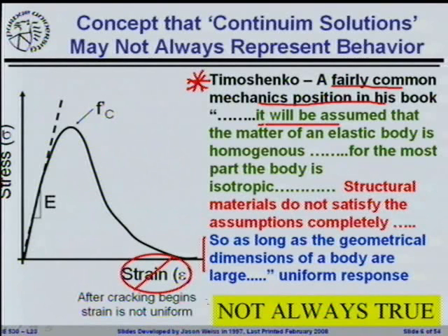The other thing that I will point out here, and this is a much more subtle thing that he points to, and this is my say no to strain comment. Okay? We are very anti-strain today. The basic idea that he assumes here is that you have to have a uniform response. Now, what I have just stated says that up until peak, you have microcracking, it's distributed throughout the body, you can have a relatively uniform response. Strain may be a valid concept on the global scale when you start to look at concrete.